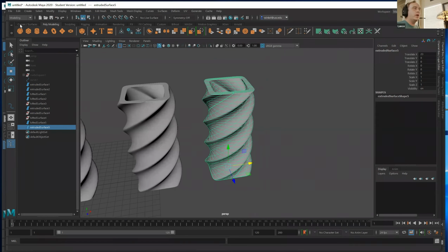Almost every 3D program that you have, especially CAD programs, and I love CAD programs, I love Fusion 360, I love AutoCAD, they work really well. Onshape, there's a bunch of really powerful CAD tools out there, but almost every one of those CAD functions, when you export their tessellation engine that goes to STL from your really nice CAD file, is mostly predicated on a concept called chord height ratios, which means they tessellate more where the curves are tighter. They tessellate less where it's less tight.